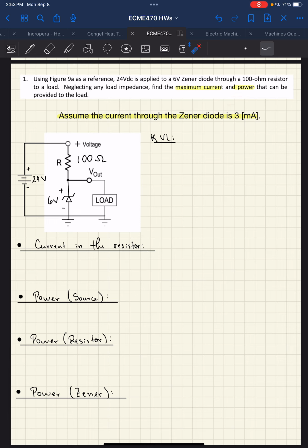So the first thing that you should do, and this is the same for both old version and new version, is to find out the current in the circuit, specifically the current that's coming out of the source. So the first thing to do is KVL in this loop over here. Current goes into the plus, comes out the minus for the resistor. The way I teach it in my lectures, I put the little man, and he walks around the circuit in the direction of the current, and I say the algebraic sum of all the voltages in the closed loop is 0.